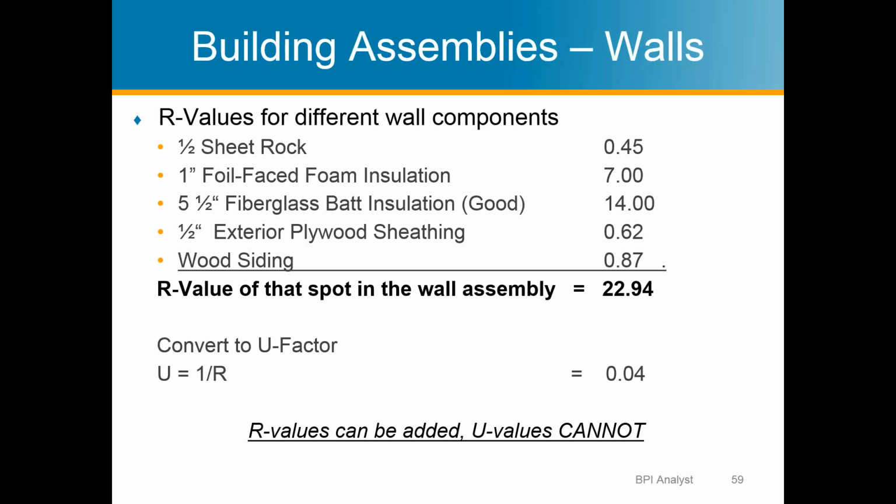So you replace that 14 with a 6, and that's the R value at the point in the wall right where the thermal bridge is happening. So we've got an R value of about 15 right where the stud itself is in this wall. So still pretty good, but not as great as the rest of the wall.